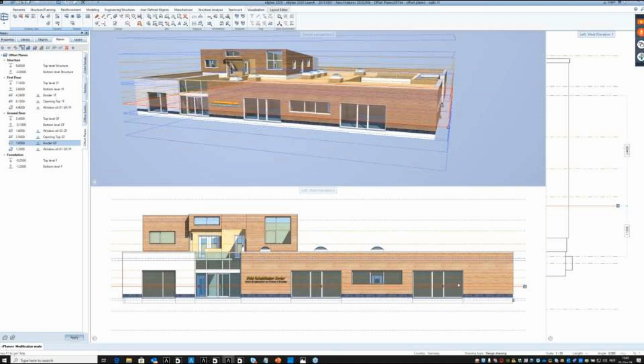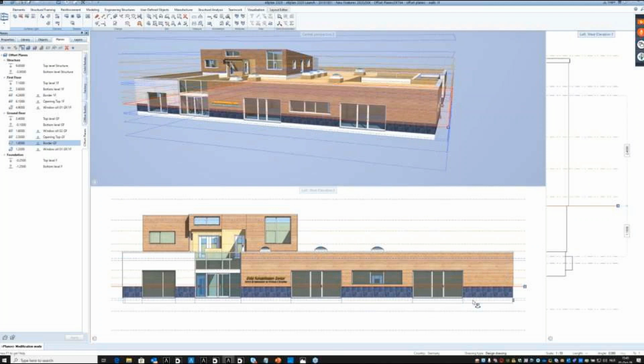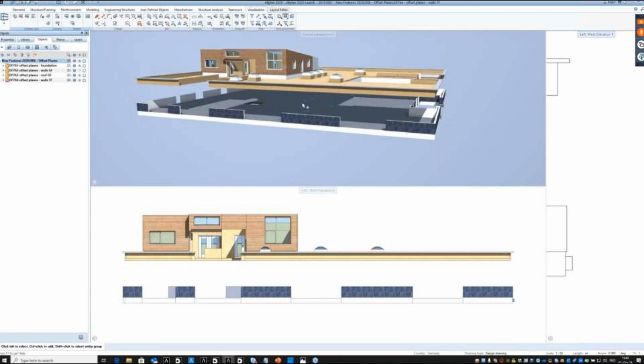And as you see here, everything is within a palette. So you go to the planes tab, you don't need to double left click on the screen and go to the modification manager of the heights and things like that. You see in real time, even graphically, what's going on with the building structure. So this is a nice feature because it encourages architects to control what they see. And also they can move it physically. You can move it by handles in the front view.